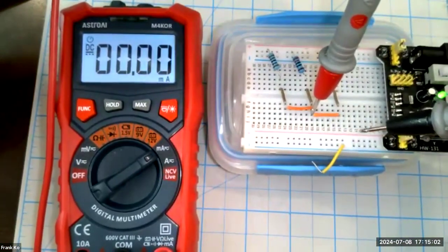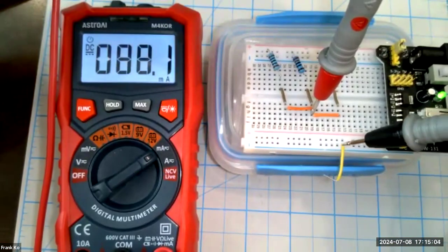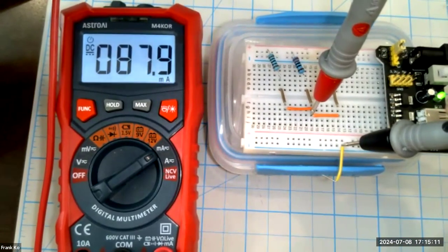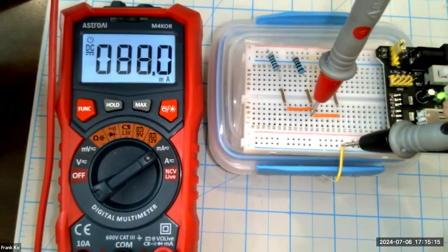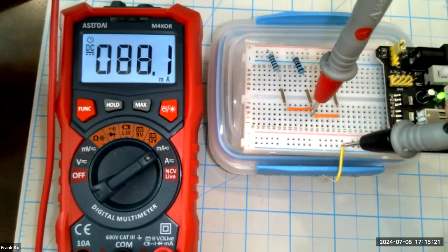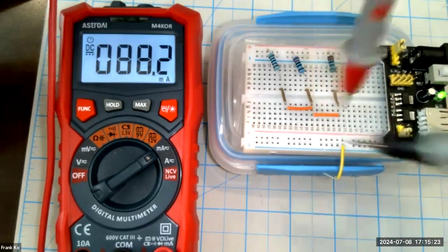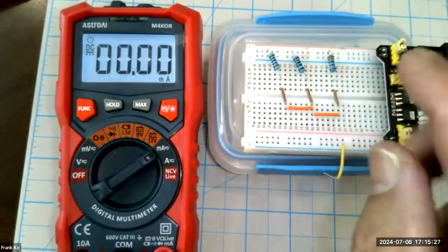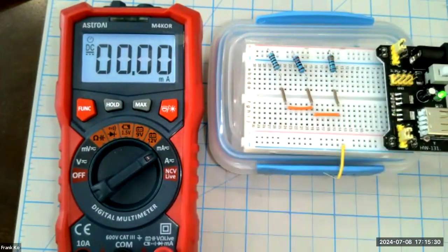So we're hoping to see something close to 87.87 milliamps. And lo and behold, guess what? I got 87.8 milliamps. That's hovering between 87.8, 87.9, rising slightly. We've got some heat action going on, but is that close to 87.87? Yeah, pretty darn good. All right, so total current is measured there. And I will continue to measure total current by creating a fault condition by lifting these jumpers.